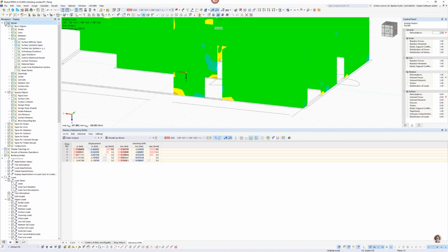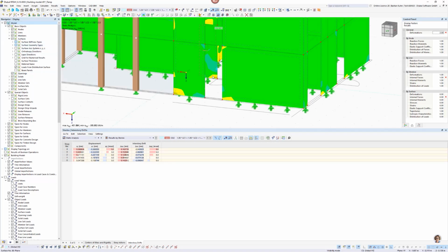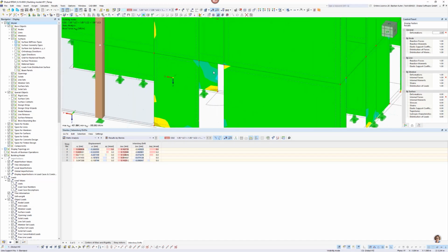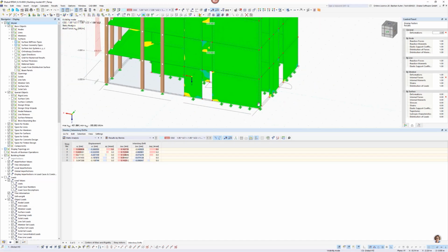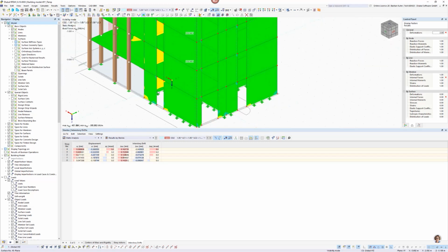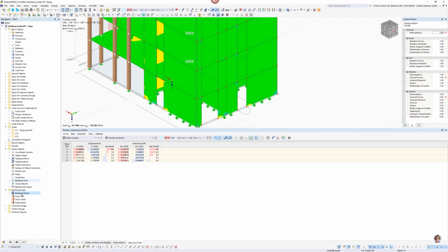So how can we regard that? I will put the model back on, and there for this edge, and maybe also this. So I have one in global X direction and maybe also this one in global Y direction. I can define in the building model add-on floor sets. They are created automatically, but I can create shear walls. So I will define shear wall in here.